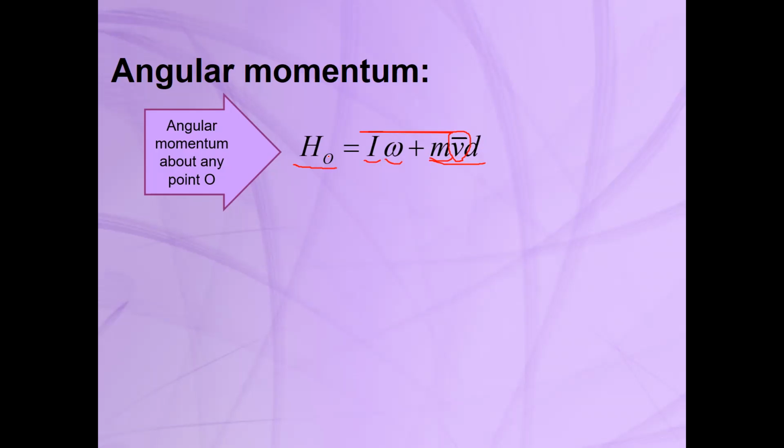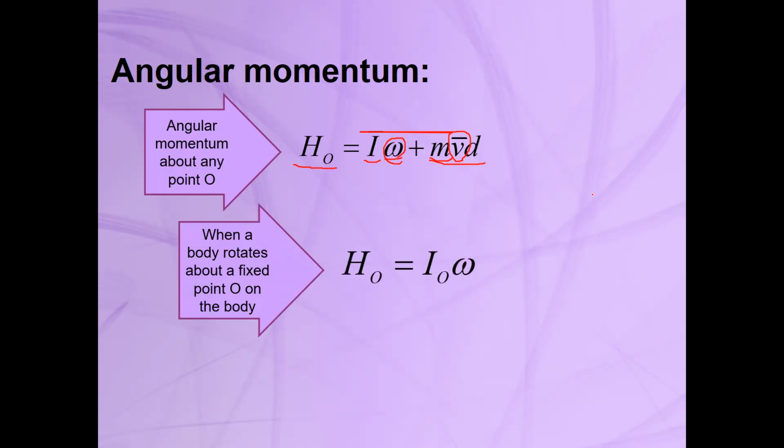You can see it's similar to when you wrote Newton's second law equation about a point other than the mass center. For example, when you calculated the moment about point O, it was equal to exactly this term. Of course, instead of omega in that equation, we have alpha, and instead of v bar, we had a bar, the acceleration of the mass center. So here you can see this is the angular momentum about point O, which is not the mass center.